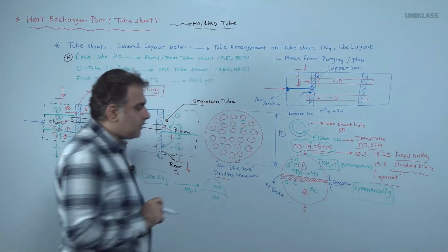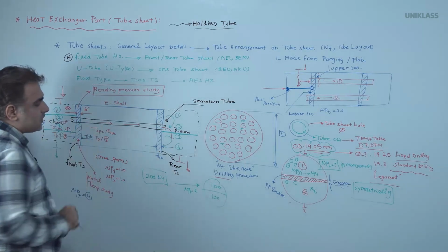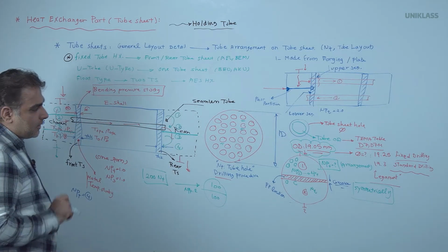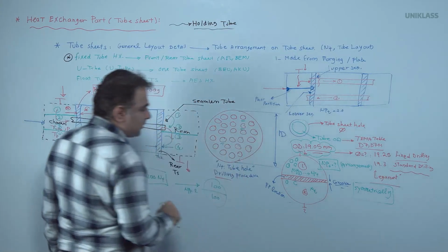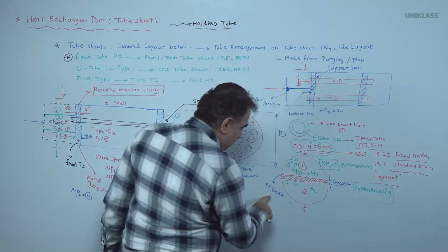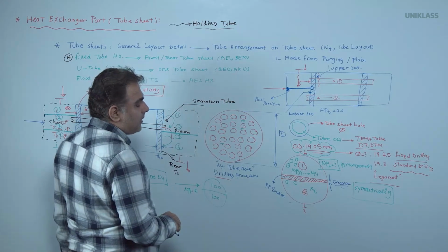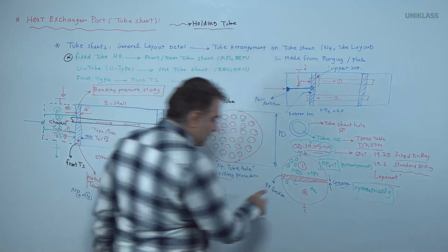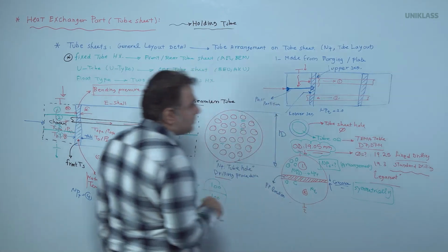Second, run the heat exchanger and model the heat exchanger based on the process requirement and show to us the number of tubes available on the tube sheet. And if you want to model the heat exchanger symmetrically based on the velocity limitation, it is so important to model the heat exchanger symmetrically and generate this drawing to the system.